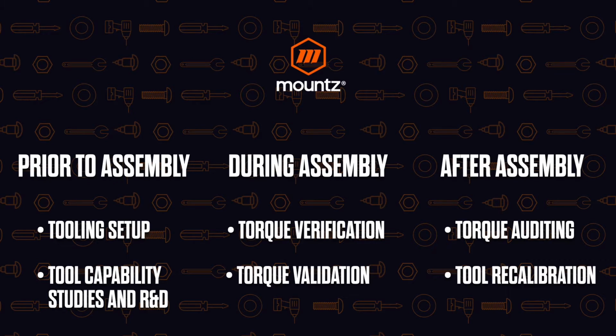During the assembly process, we can do torque verification and torque validation. And this would be where we are actually placing the transducer on the tool while it's in use, or bringing a calibration cart to the tool, checking it on the line, and then putting it right back in service. And then we can do the testing after the assembly has been completed. And this would be done with torque auditing, where we would actually look at fasteners that have already been assembled. And we could also do tool recalibration. And again, we'll touch on that here as we look at each particular area within the process.